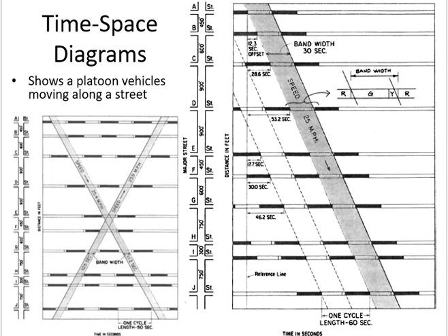So I need to know how much time the vehicle will take to go from here to here. How do I calculate this time? Distance over speed. So you need the speed of the vehicle, the average speed at which it will go from here to here, and you need the distance between the two intersections. Distance you already know, right? You already plotted it. Speed, obviously, you have to do some sort of traffic study to know. So for example, this distance is 450 feet plus the width of the intersection.